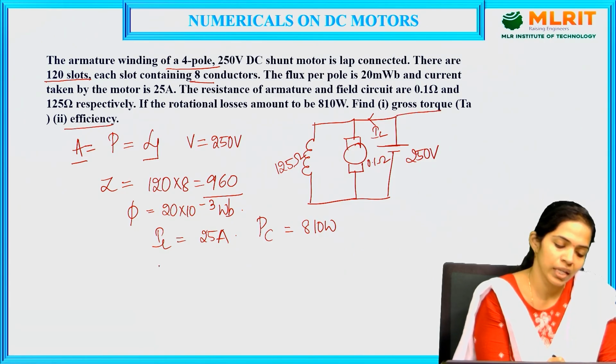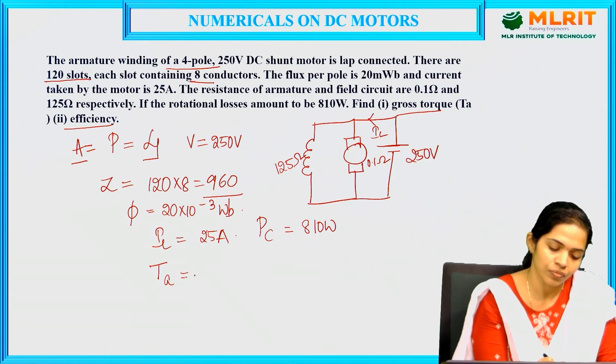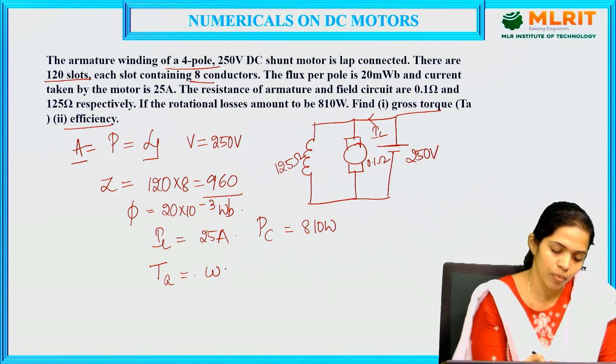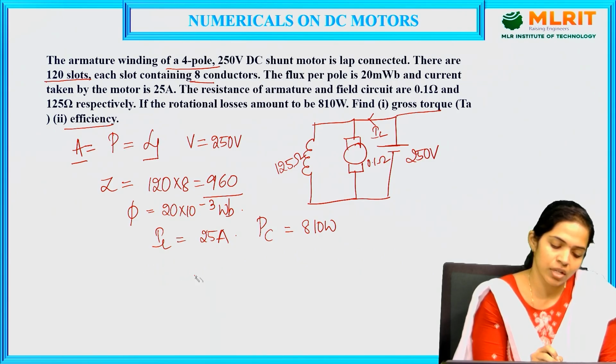We know that the equation for the torque is nothing but T = P / omega. Let us again equate the mechanical powers for calculating. So now your mechanical power is nothing but omega into torque, which is again equal to EB into IA.